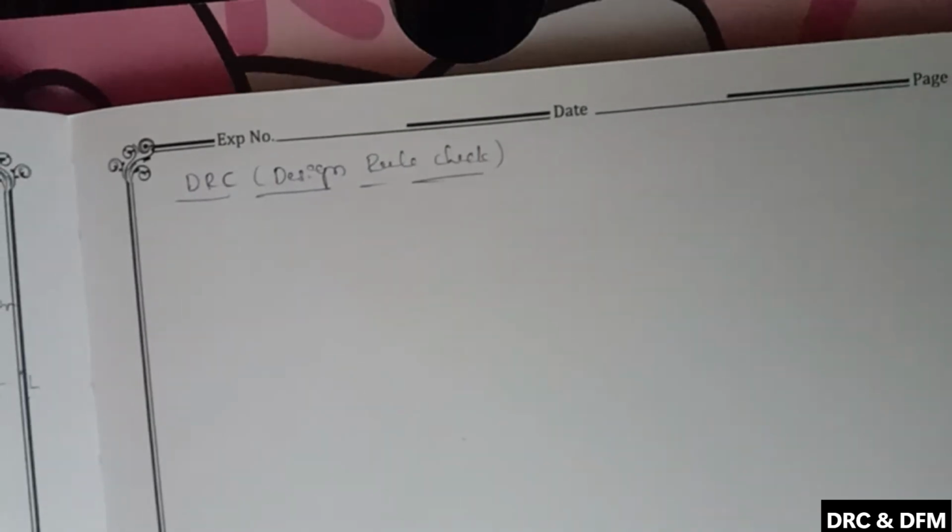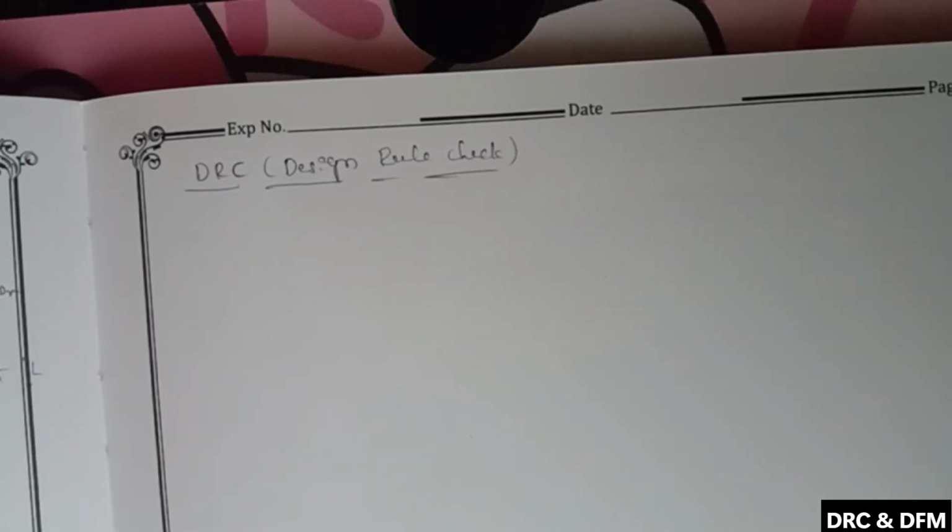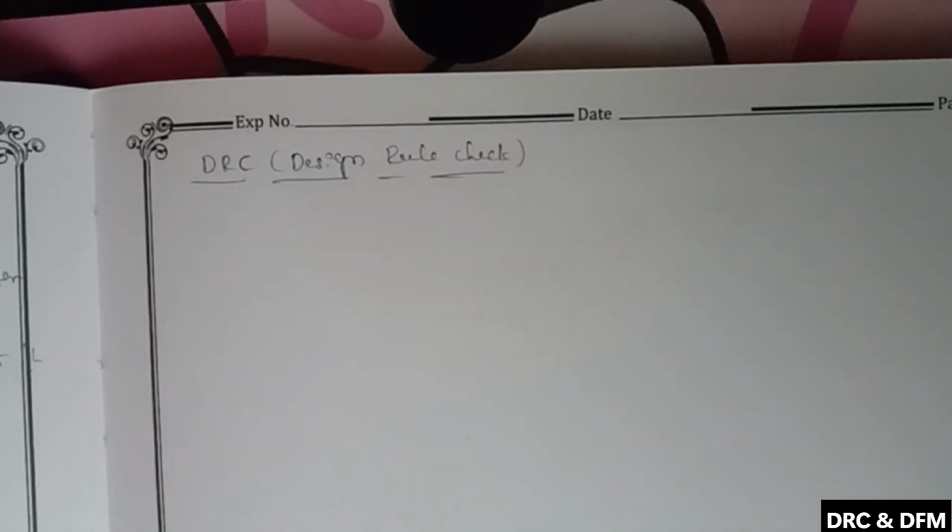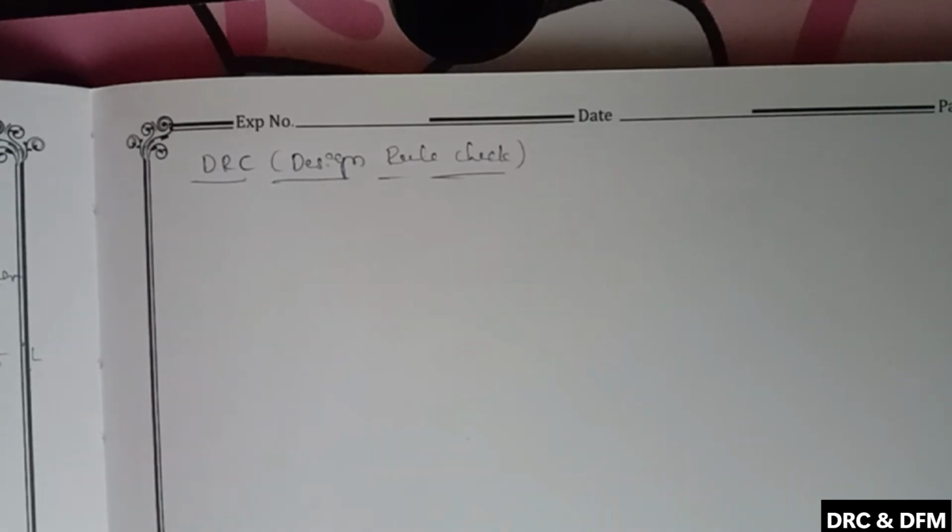Mainly we are doing DRC and LVS. Why is it needed? Normally we want a chip which is robust, should work properly, and performance should be perfect. To check this reliability, we also don't know whether it works or not, because fabrication will happen. After fabrication, we want maximum yield. To increase the maximum yield, we go for the DRC and LVS, which gives us reliability.